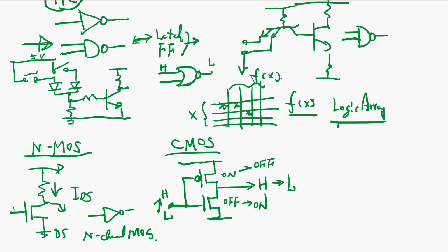Okay, the MOS device fan out is all to the gates, which is capacitive. So the problem is that switching speed depends on how quickly you can charge this capacitor and discharge this capacitor. Okay.